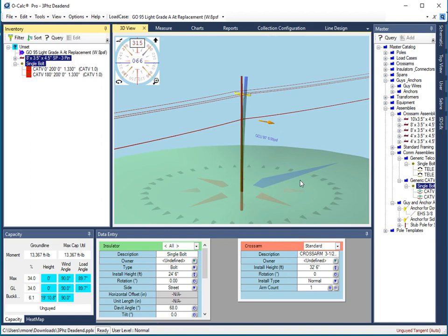So this new relative setting tool is very powerful, and in addition to being used in regular pole editing like I'm doing here, it can also be used in stringing. So if I say I want to string something on my pole, I can now say, in line design mode, I want to string everything I'm stringing so that the group starts 10 feet below bottom power, or so on and so forth. So you can see how this saves a lot of mental arithmetic and mental gyration in order to set the relative heights of various things.